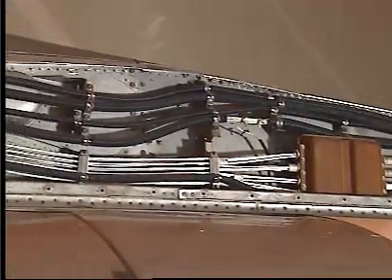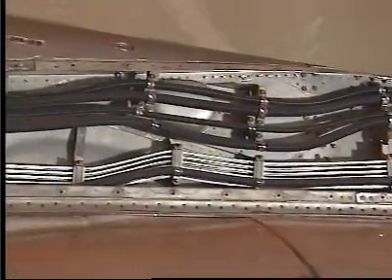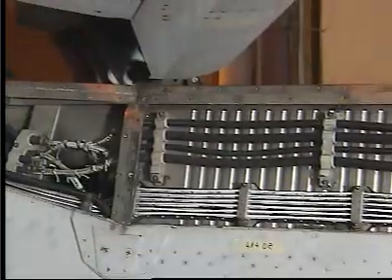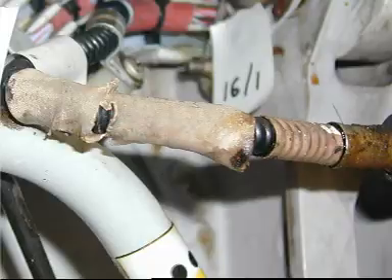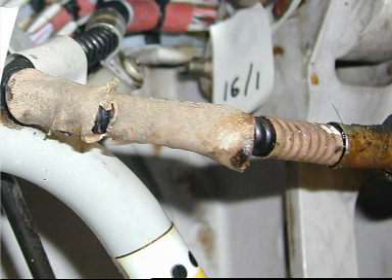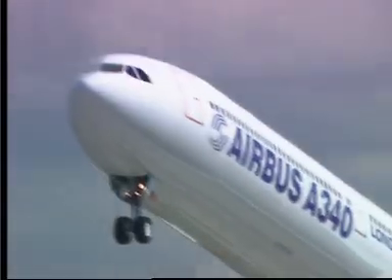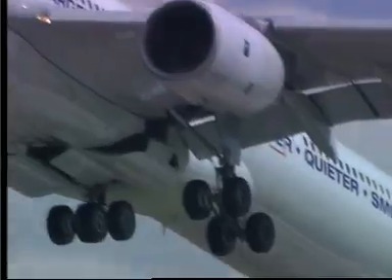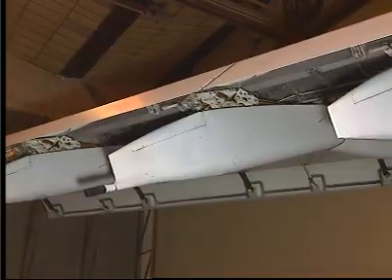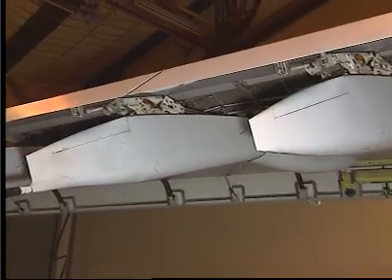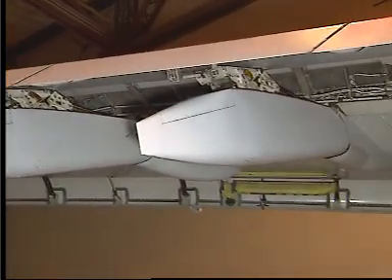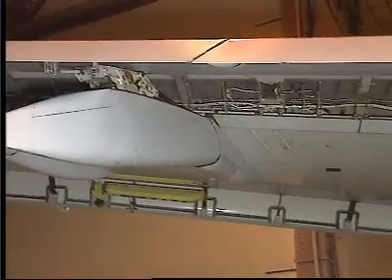The conduit protecting the wires and the wires themselves could be damaged through vibration. Consequently, damage to sleeving and conduits must be repaired in accordance with the Airbus technical documentation. The leading and trailing edges are exposed to vibration and other environmental effects. These areas are difficult environments for wiring installation whenever the flaps and slats are extended.